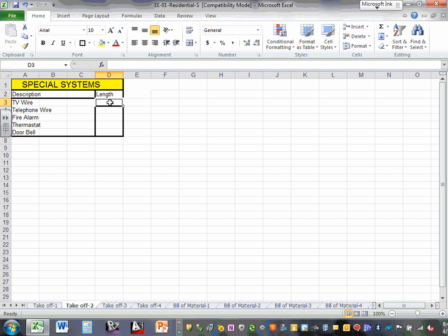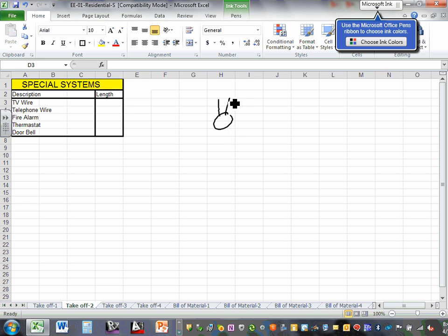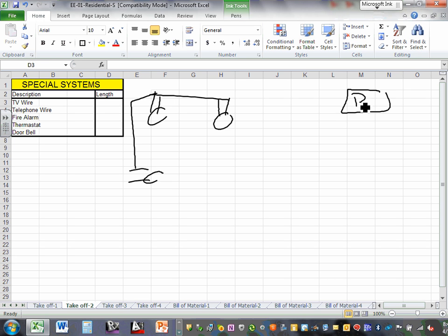Again, remember, you're not going to finish everything today, guys. You need your scale. Write yourself a note. As you start measuring distances, please move with right angles for this project. It gets you into the conduits layout. As you move from point A to point B in your system, here's one point A and a bunch of others. At the end, here's my panel right here. I'm going to go right all the way to the panel. That's how I would like you guys to move.